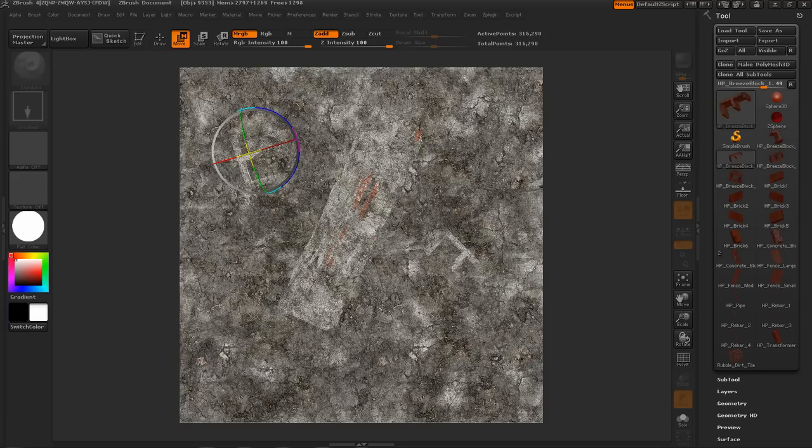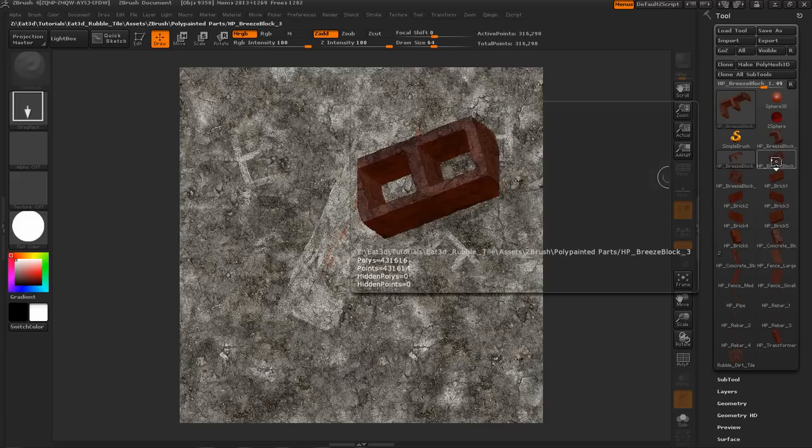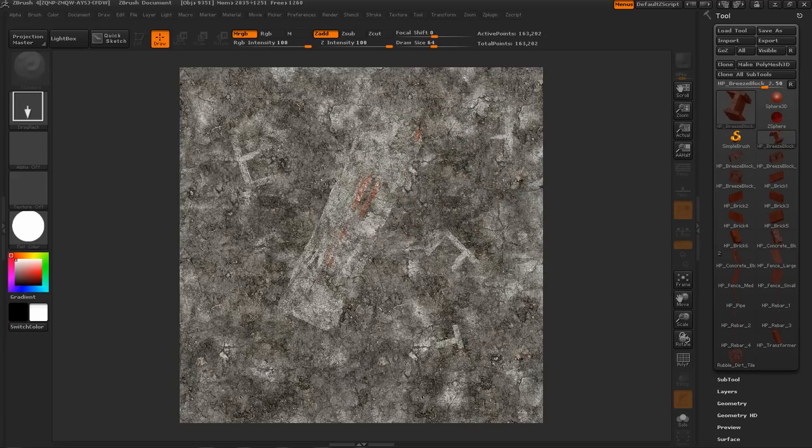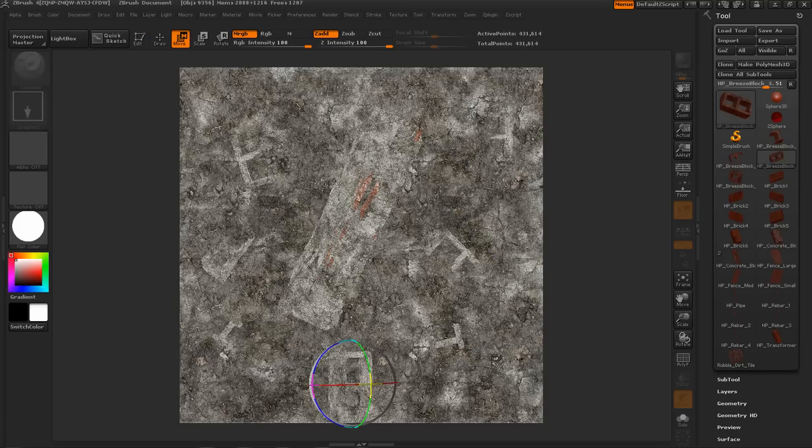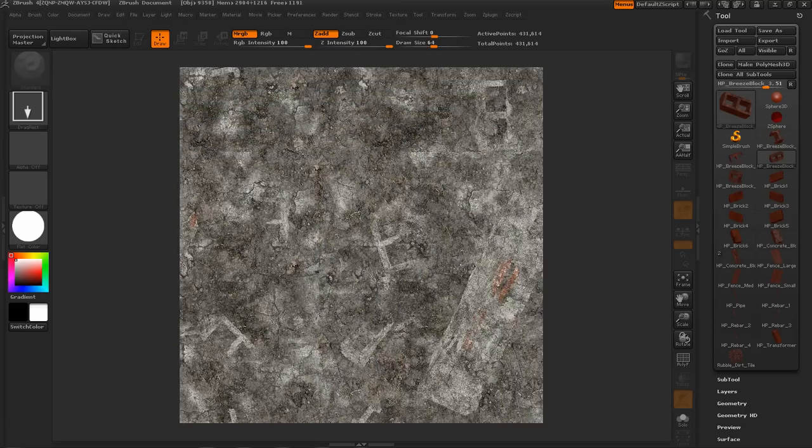And then you're going to drag out another one. Basically, you want to try and fill up as much space as you can here, changing the height and getting as much variety as you can. And you can switch between move, scale and rotate as many times as you want, but if you press T and go into edit mode, then you get the transform widgets. But once you do that, you can't change the height of the mesh, so be very careful when you do this.